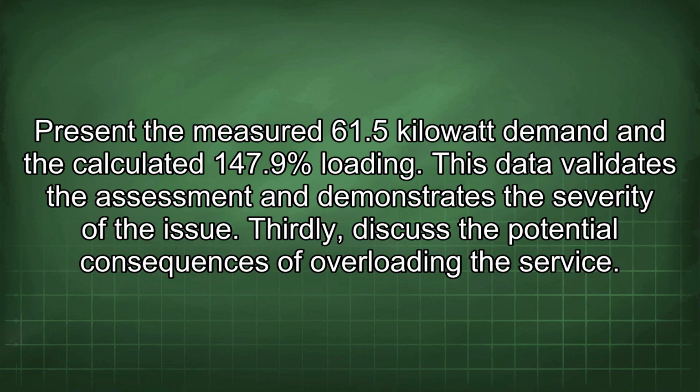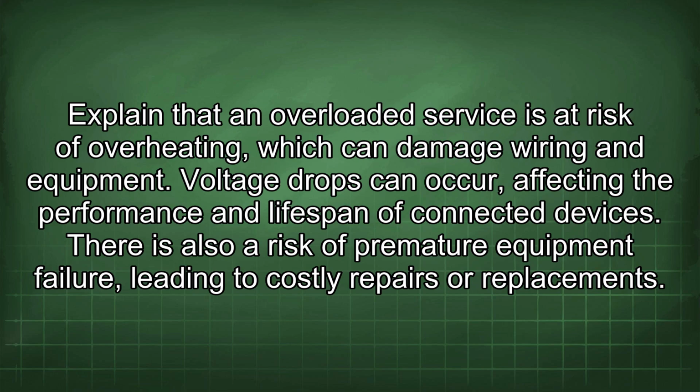Thirdly, discuss the potential consequences of overloading the service. Explain that an overloaded service is at risk of overheating, which can damage wiring and equipment. Voltage drops can occur, affecting the performance and lifespan of connected devices. There is also a risk of premature equipment failure, leading to costly repairs or replacements.